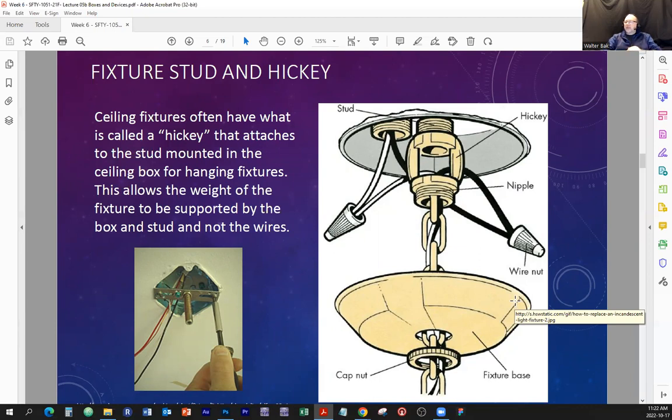Some of the devices, such as a ceiling fan, are heavier, and they can't just be mounted on the drywall ceiling, for example, or in ceiling tile, because they're just too heavy. If you mounted the ceiling fan so it's held only by the drywall, and it's on top of your bed, that ceiling fan can come down on your face while it's still spinning, and that would, of course, write it down, kids, not be a very happy situation. Okay, so there you go.